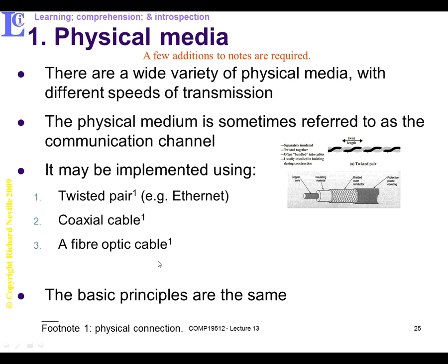Now we move to the top of the range, fiber optic cables. Now these cables nominally transmit light pulses down the cable, and they internally reflect. They normally have a light guide in the middle, some cladding, and then a jacket to try and make sure these fragile light guides don't break. So I've actually got one of those in the lecture I'll show you, which can be used for subsea transmission. You'll see it's pretty physically big and the light guide in it is tiny. So here's 3 different media with 3 different characteristics. The most expensive and the broadest bandwidth is fibre optics.